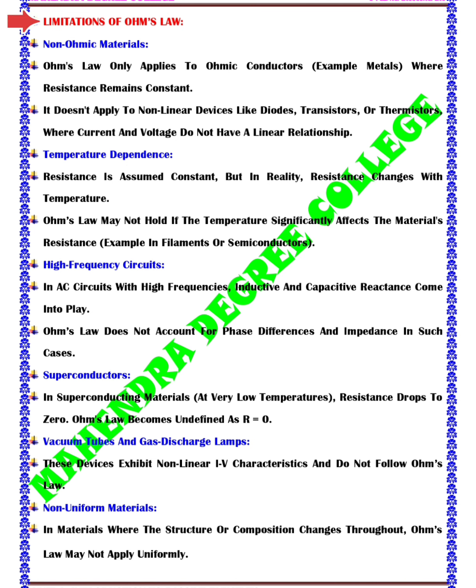Next, we discuss the limitations of Ohm's law. First one, non-ohmic materials. Ohm's law only applies to ohmic conductors, for example metals, where resistance remains constant. It means Ohm's law, stating V equals IR where resistance R is constant, only applies to ohmic conductors like metals. It doesn't apply to nonlinear devices like diodes, transistors, or thermistors, where current and voltage do not have a